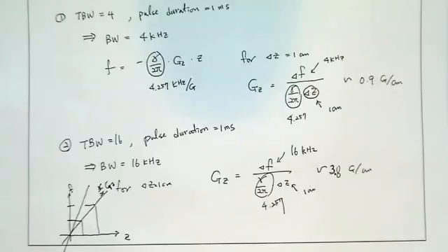RF bandwidth is limited by the B1 amplitude and duration, and the gradient amplitude is limited by the hardware. You can't have an infinite RF bandwidth, or infinite gradient amplitude. So there is a limitation, and based on those limitations and a given design specification, in this case the slice thickness, you can maximize the quality of your slice profile.